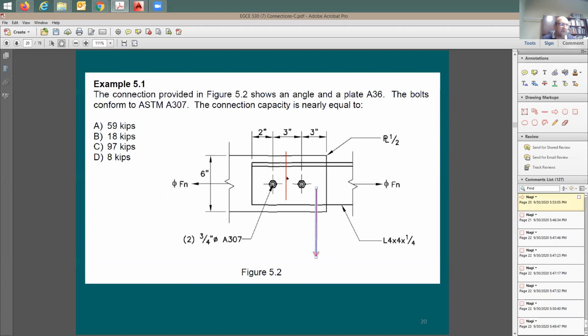Another condition for this, if I'm going to have here the center of the bolts in this direction, now let's talk here about the X direction. Center of rigidity of these 2 bolts, let's say it's going to be right here. If I put this bolt right here in the middle, you can just take this force, split it equally on these 2 bolts.